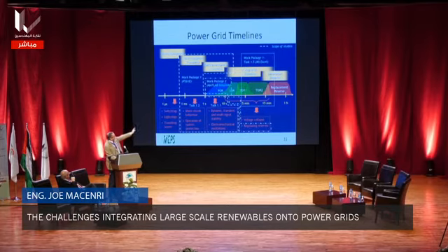You can see then we have POR, SOR, these are all the various reserves, and these are the types of issues that operators of grids have got to be thinking about the whole time, setting up all of these various reserves. Some of them, with the timescales they're operating in, are automatic, and others are dispatchable. So anything generally greater than about 15 minutes, you're into generation dispatch. But in fact, it's not even 1 hour. That graph continues outwards into days, seasons, years and decades. If you're looking at energy policy, you'll be looking out at decades in the planning of the entire power system.